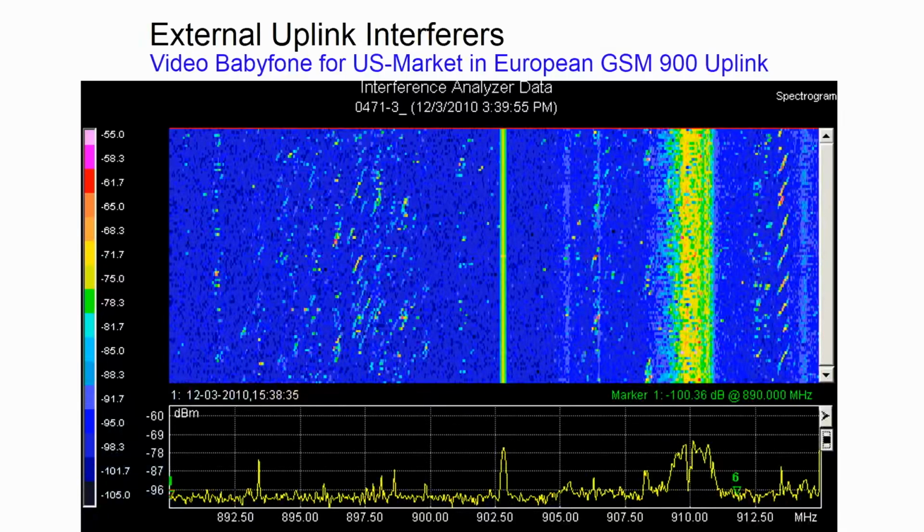And there are some more sources from the real life. There's a GSM 900 frequency. It's a waterfall diagram that you can see here, and this waterfall diagram will show a spectrum analysis on the bottom, and it shows it as a history plot. Where blue is deep water and low noise, and yellow and red there's a high level, and you can see very well here. And this kind of analysis without waterfall diagram it's very hard to diagnose an interference. Very few look exactly like this as a continuous carrier with a continuous video signal.